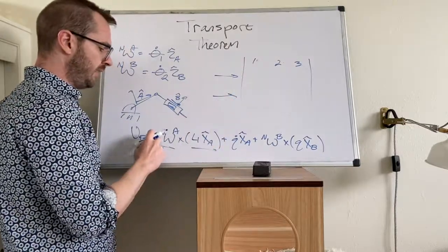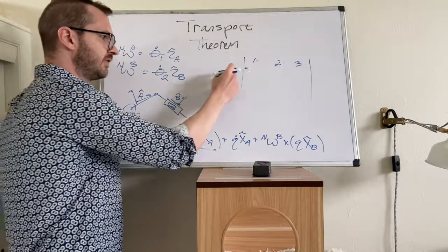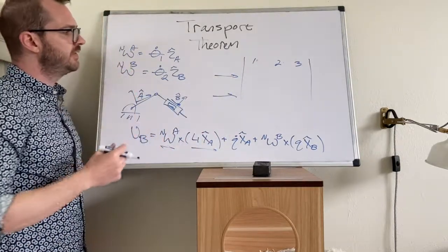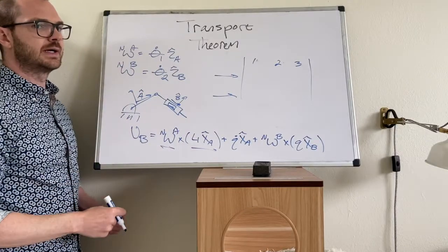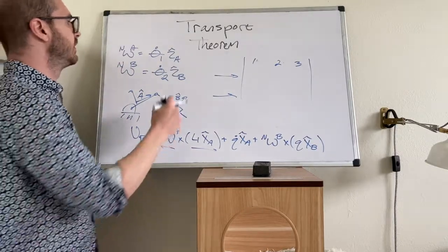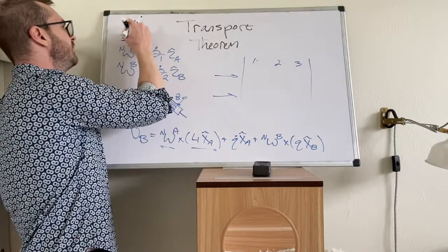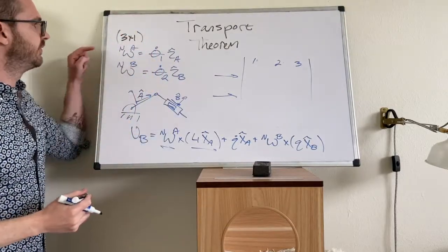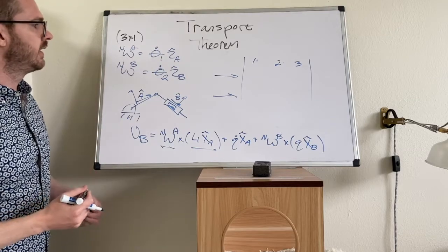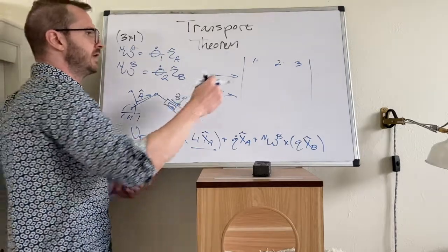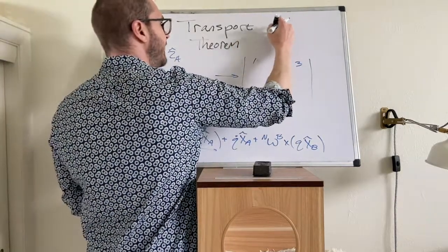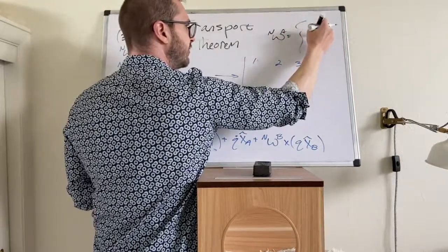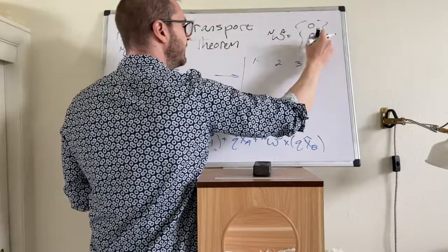So omega into A, we have to load it into this first row. Omega into A, I've got it written right here. What are the dimensions of omega into A? This is a 3 by 1, position vector. These omegas are 3 by 1s. And you can think about them if you need to, like this. We could say omega into A, I can write it as a vector, and it's 0, 0, theta 1 dot.